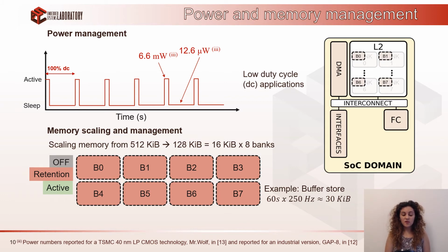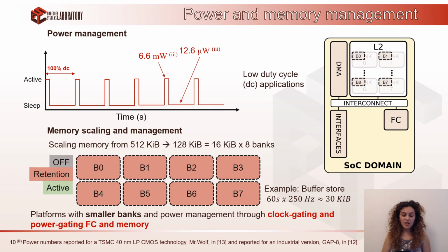This can of course be scaled to the smallest feasible resolution for the needs of the application, and in fact it is necessary to have platforms with smaller banks and apply power management through clock and power gating of both the main processor and the memory.